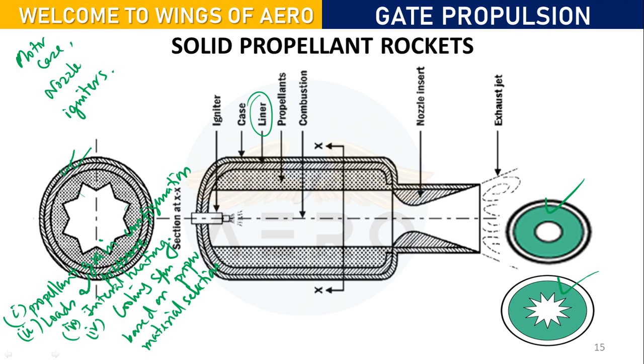We need to take care of this motor case. First, the type of propellant grain configuration, and the amount of load and pressure acting on this particular chamber. Then what the possible internal heating, aerodynamic heating, and thermal stresses and strain will be. Then the cooling system: how we can make an effective cooling system based on proper material selection. Clear? Have you noted?